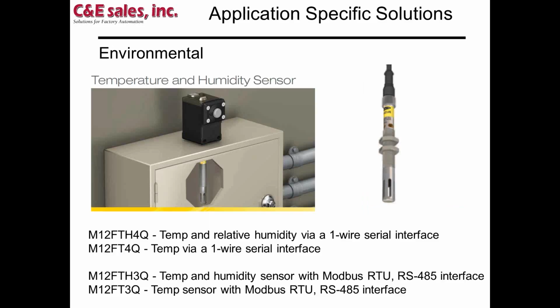And then there's two different serial interfaces, depending on the network. Mainly the one-wire serial you're going to use more with the DX80 network, and then a Modbus device more for the multi-hop. Just a different communication network between it and its local node.